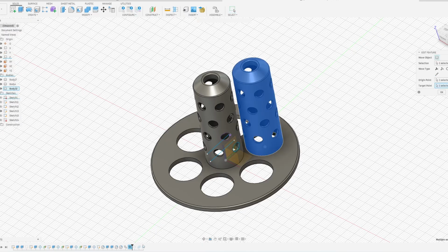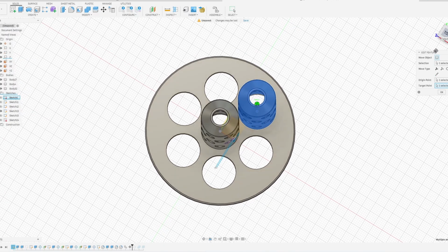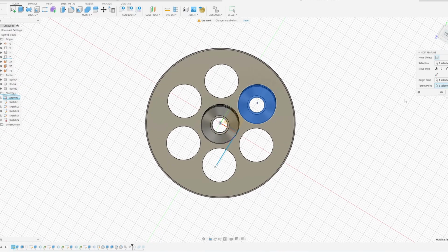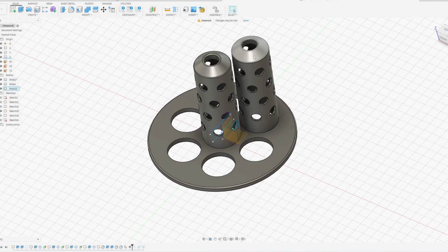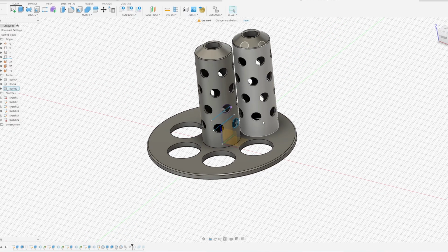We're right here, and then we're going to select this feature, this object, this body, and then we're going to move it from point to point. So here, what I decided to do is move this feature from point origin, this one right here, into the target point, which is going to be right at the center of this circle. And you can see the X, a blue line here that crosses 2 points, and that's the object. Once my object is already copied, now I can